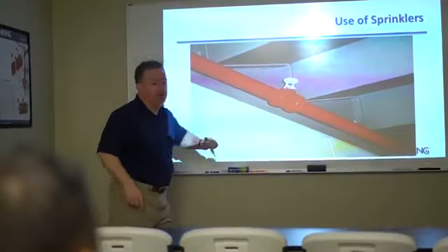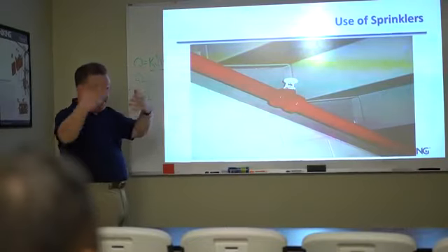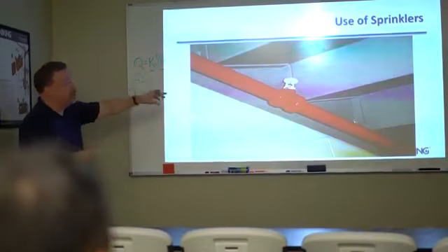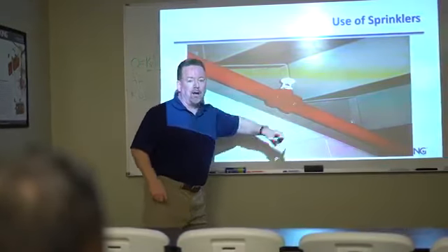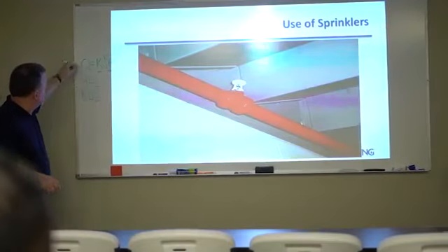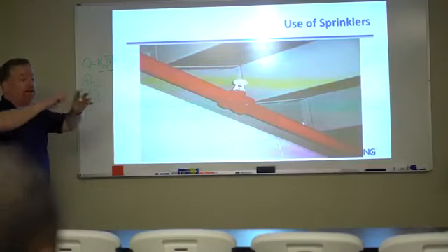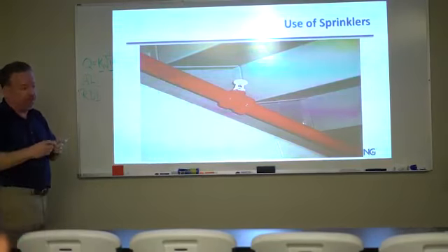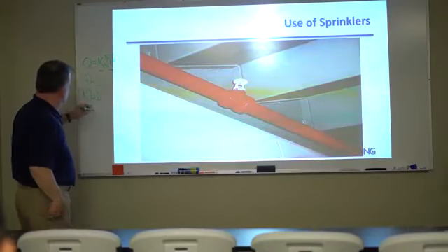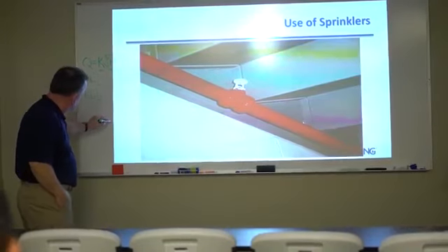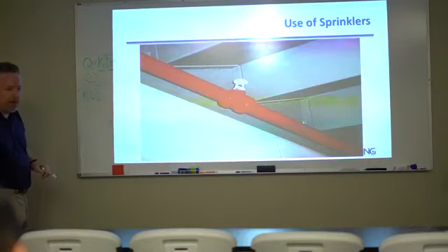Well, this sprinkler has what we call an ADD, or a capability of delivering water. The actual delivered density, okay, is going to be sprayed out of this sprinkler, depending on K and the square root of P. That's going to be the actual water that comes out, the actual density over each of those square feet. Okay? So now we have a sprinkler in the middle of our room, and we have all of this water, and we have this space that it's required to cover.